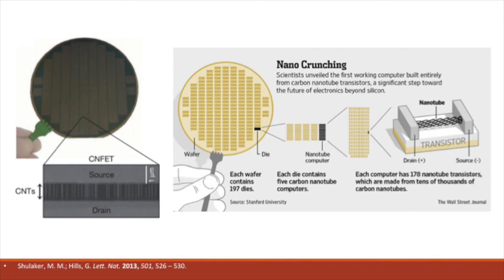The fabrication of the processing chip was insensitive to the relative distribution of nanotubes within each unit, as seen in the nanotube spacings in the SEM image. This tells us that improvements to the fabrication process will have to be made to construct more ordered, viable chips for everyday operations. However, this imperfect chip still enabled the computer to run stored programs and offered completely reprogrammable capabilities.